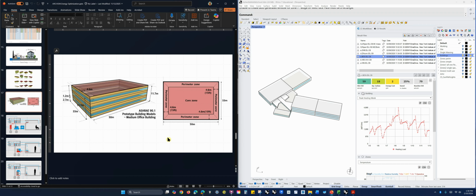They're going to come in 15 feet from the exterior wall, and one reason is daylighting. That's the first limit, a typical measure of a daylighting zone, where you have a clear definition of how much light is getting in based on its facing of the building. But also, each of these exterior walls is going to have a different amount of heat loss through it based on the amount of sun hitting it, right?